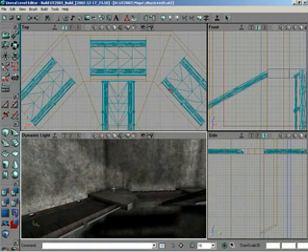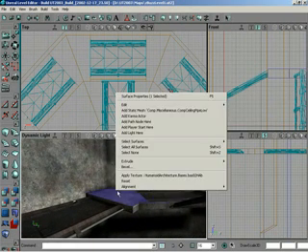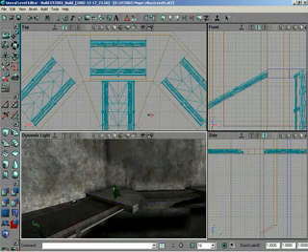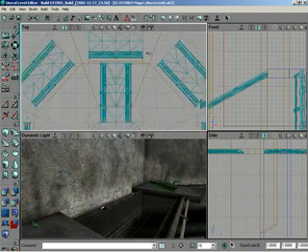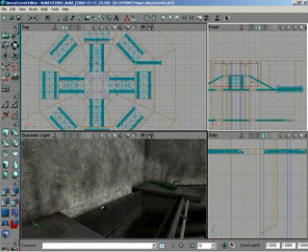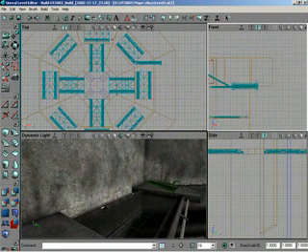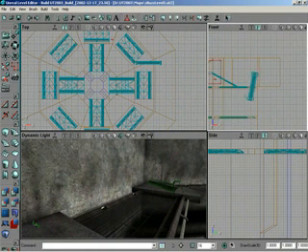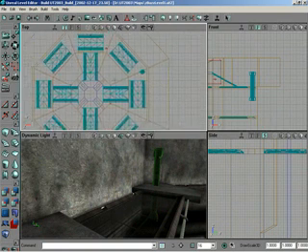So I'll start at the top. I'll right-click and add one of those. We'd rather have it vertical, so let me go find a good view to rotate that in. Let's see, how's the front? Yeah, the front will work good. I'll Control right drag, throw it vertical.